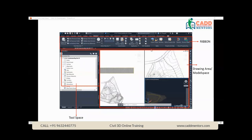And this is all about the ribbon, where if you see the Home tab, it has some content about points. When I say points, you can interlink this with the survey data. Generally when you do a manual survey on the site, you have the x, y, and z. In the same way, every point will have an x, y, z. In the same way, in the Create Design panel you have alignment, profile, corridor, intersections, assembly. These are the tools which we frequently use to make our alignments or geometric designs.